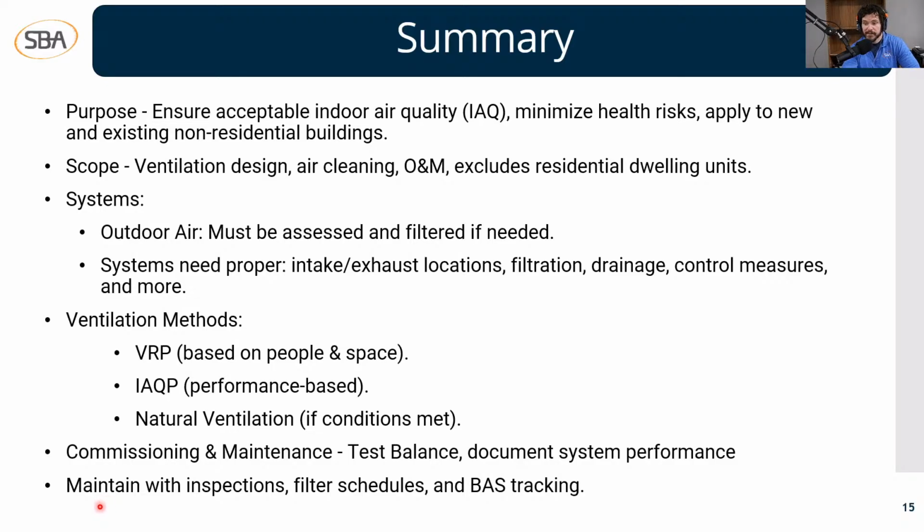So in summary, I'd like to point out that it protects the people, it makes sure that the air is healthy, and that it applies to almost every commercial project we work on. So from proper air intake design to MERV filters, from VRP calculations to indoor air quality testing, it's all in the 62.1 standard.